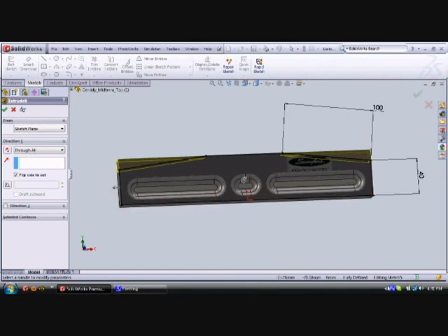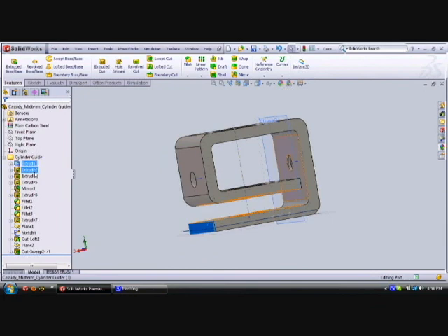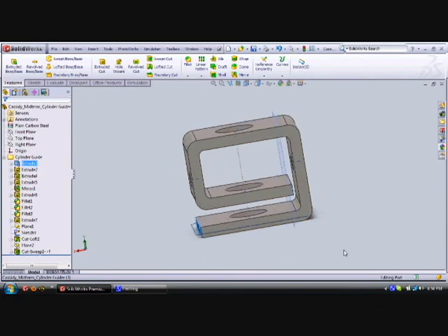This required much less geometry than it would have if I would have defined each feature separately and not used the on-edge geometry. There are some ways that this design could be improved or refined. One way is for this guide, cylinder guide, to be formed out of a sweep instead of the numerous extrudes, cuts, and single mirror. It could be swept using a number of guidelines and pathways.